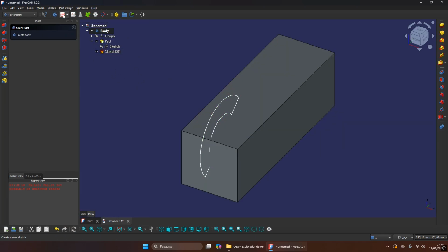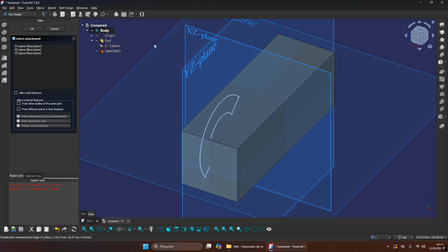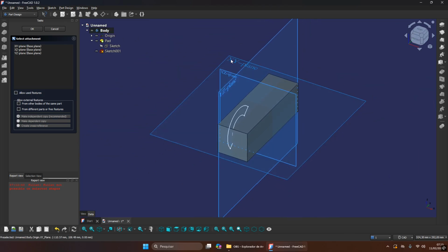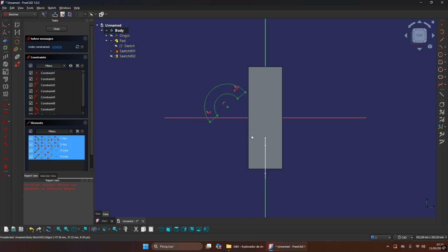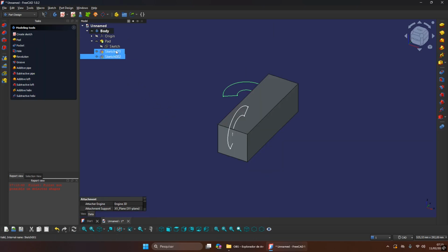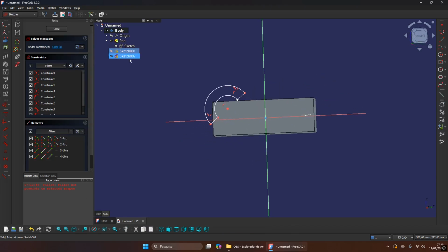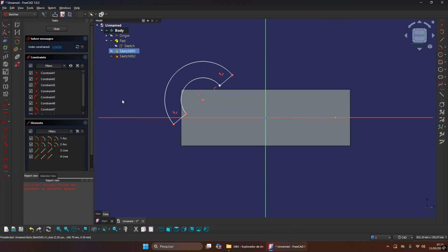I want you guys to create a new sketch at the XY plane. And here, Control V. You can paste here. Okay. Let's just leave this profile and this sketch for now. Leave here and go back to sketch 1 and let's continue.